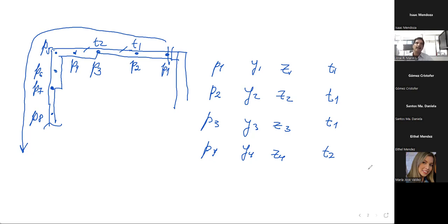So especially on the side, try to have at least 1 point at each end and at least 1 intermediate point. So you can describe the curvature of the distribution in a better way. If you include at least 2 points on the side and also on the double bottom, that would be better. You will see that the distribution has some curvature, and that could be well integrated. Okay, if there are no questions, then I'm going to switch terms, and now I'm going to go back to the material.